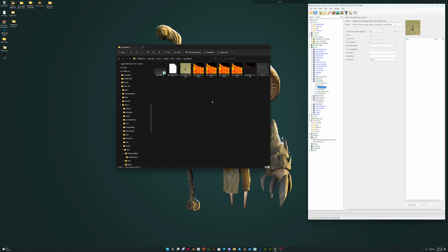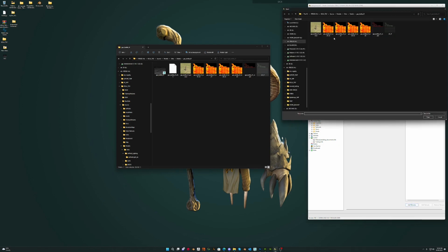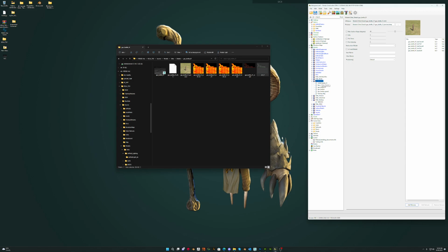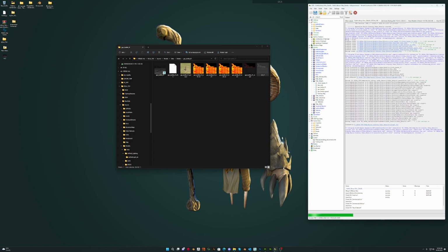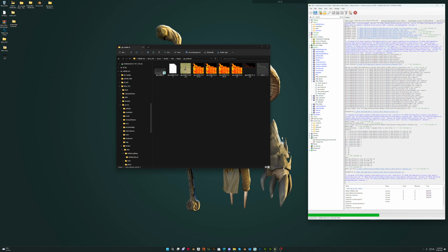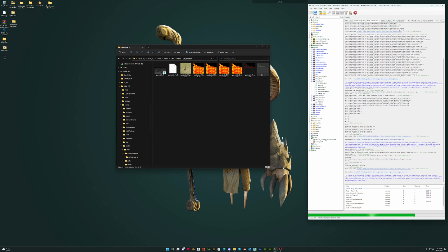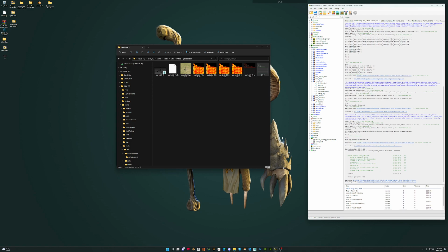Now what I need to do is add the other files. So I add LOD1, LOD2, and the mask, nothing else gets added. If there were SI maps in there, you would add the SI maps, which is a good thing. Then I basically build the library themselves, checking that there are no red errors being generated. Any red lines or anything, they need to be addressed. As you can see, that was perfect.